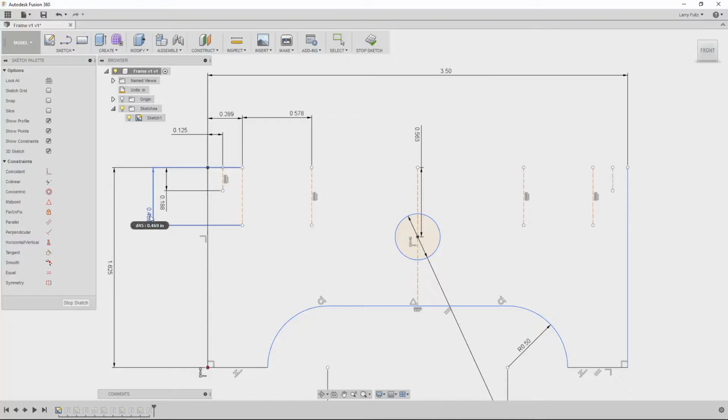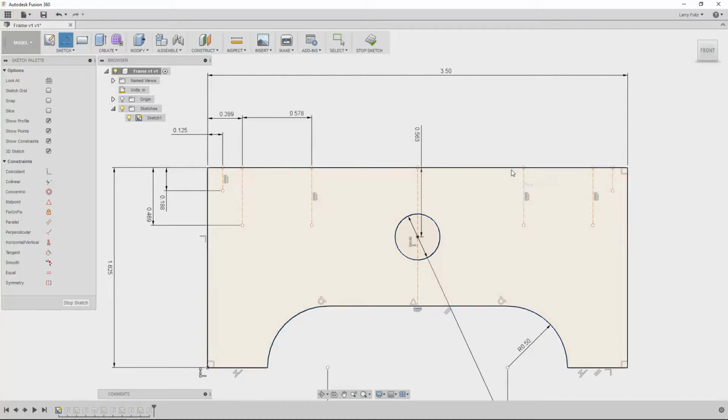Enter. Okay, so first thing we want to do is create a line from endpoint to endpoint to replace that line. We'll snap all of these endpoints on the line to that line, and then we'll start applying our symmetric constraints to it. Okay, so let's select L for line and go from endpoint to endpoint. Now the next thing we want to do is make sure all of these points end up on that line. Let's redefine those points as coincident points. So do that.